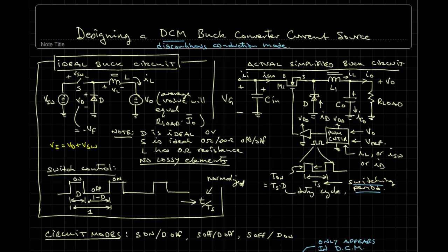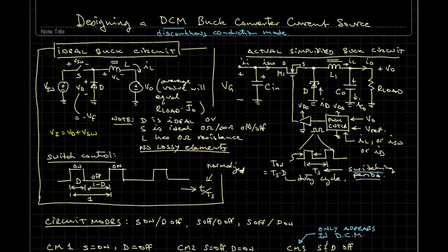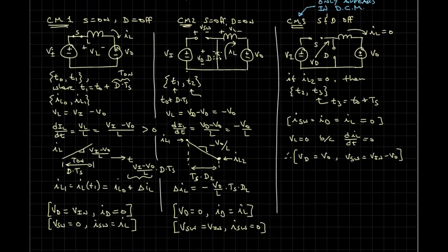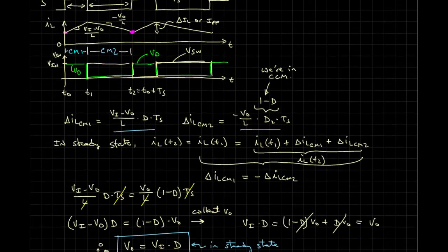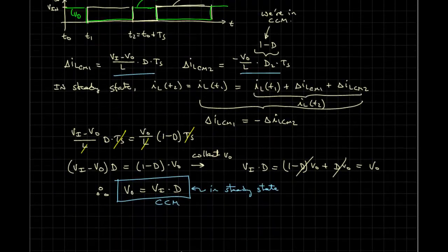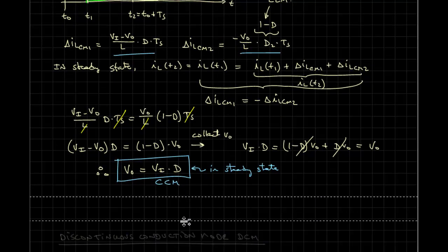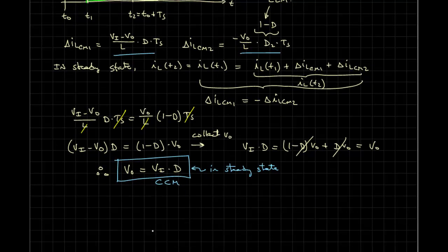and we demand more current or less current. Now, in any real converter, there will be some dependency, and that's why you need a feedback controller that measures the output voltage and adjusts the duty cycle. But a lot of times it doesn't have to adjust it very much. Now, there's a lot of additional things that we can calculate related to this operation mode, particularly some of the stresses on the components, because you need to calculate stresses and losses. And so maybe I'll spend a couple minutes here. We'll work through some of the major ones.